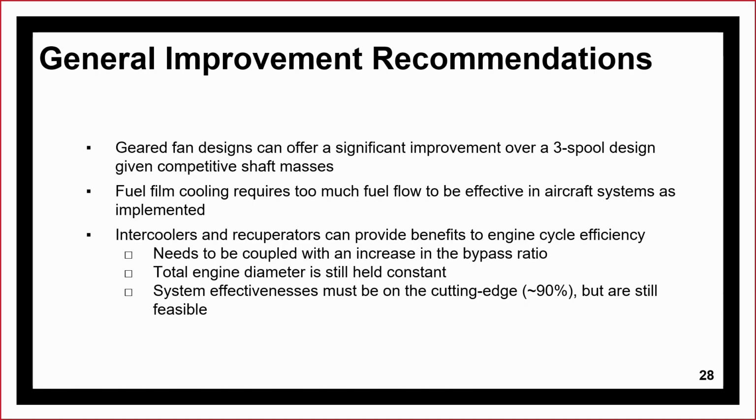So in conclusions, geared fan designs offer significant improvement over traditional 3-spool designs given competitive shaft masses, and that's why we're starting to see them enter the marketplace. We also found that fuel film cooling requires too much fuel flow to be effective in aircraft systems at this time. And finally, intercoolers and recuperators can provide benefits to engine cycle efficiency, but they need to be coupled with an increase in bypass ratio or other modifications that we were not able to explore.